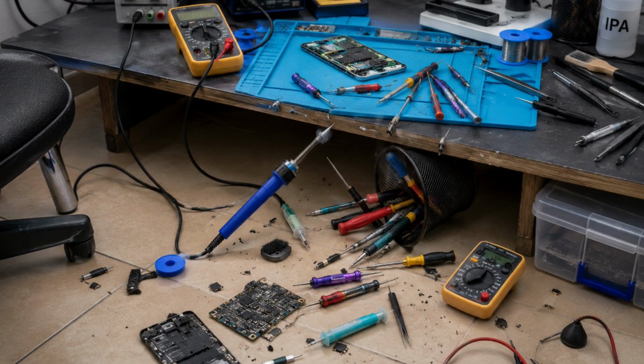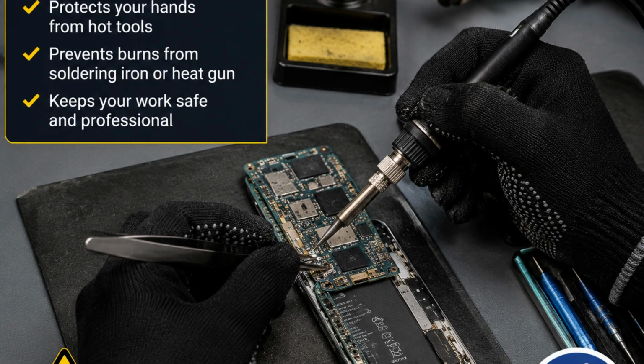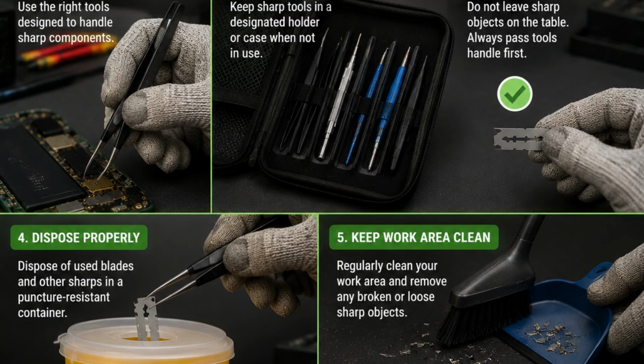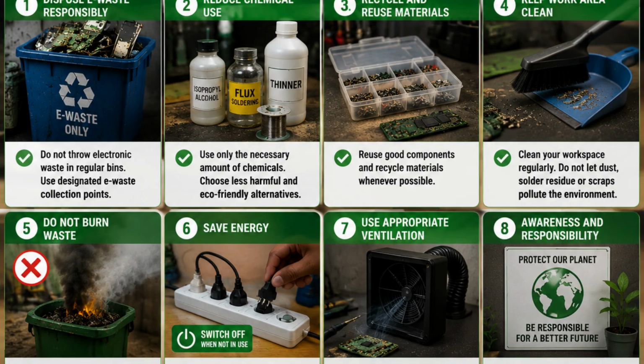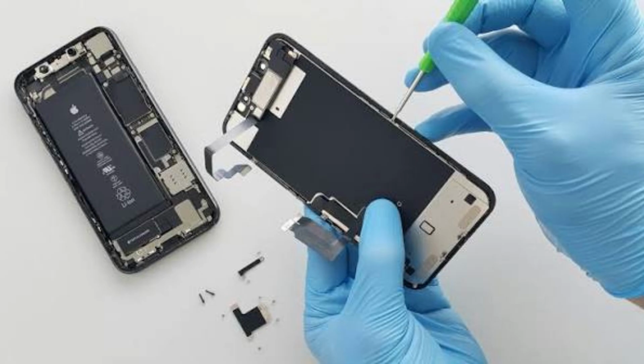We also learned how to prevent these hazards by using well-insulated tools, wearing protective gloves when necessary, keeping the soldering iron in its holder, unplugging electrical equipment when not in use, properly storing and disposing of sharp objects, keeping the workplace clean and organized, and disposing of electronic waste responsibly. Remember, a good technician is always a safe technician. Safety should always come before repair.